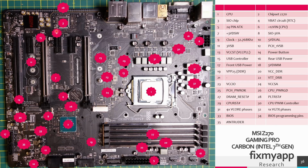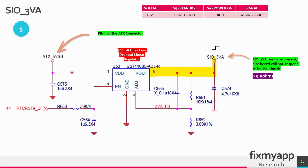This voltage regulator will create 3.3 volts and it will power the Super I/O chip. The voltage rail that this regulator creates is called Super I/O 3 volt auxiliary. This voltage regulator will convert 5 volt that comes from the standby power rail from the ATX power supply. It will convert it to 3.3 volt. This voltage rail is a secondary power source used when the main power supply is unavailable or off.